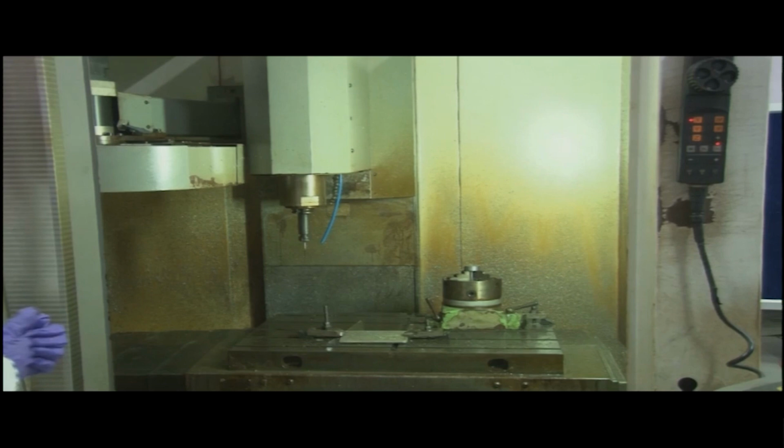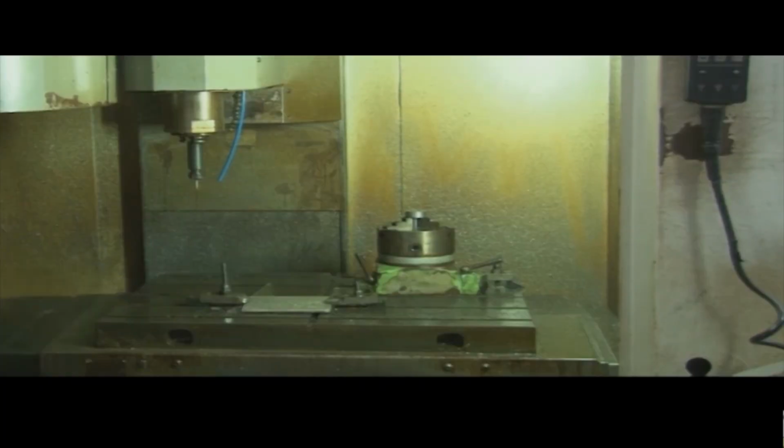So, the most important point here is referencing, which we will see now. In the software we had the reference, that is X0, Y0, Z0, that also has to match with the reference of the machine. So, how do we put that? Now, this table is big, because the tool does not know where the workpiece is mounted. The hardware and software have to be integrated, have to come in one plane and one point.